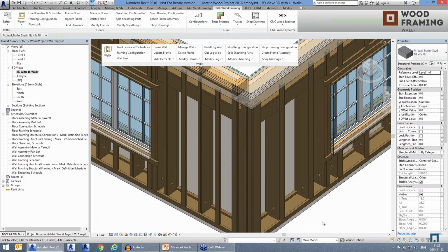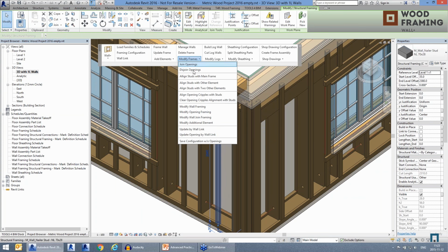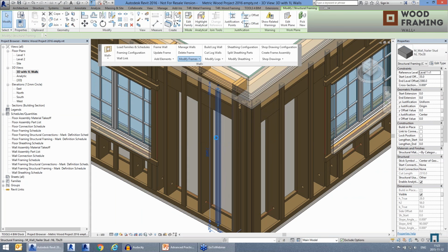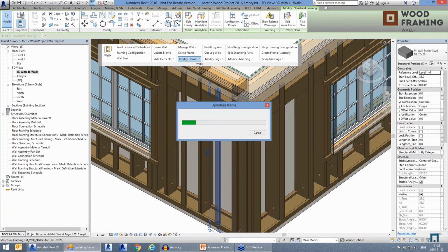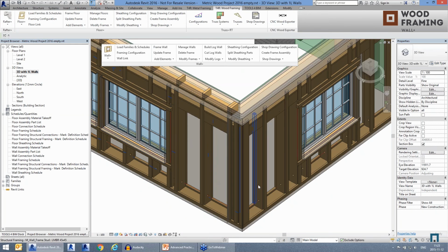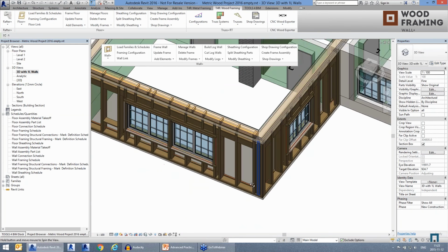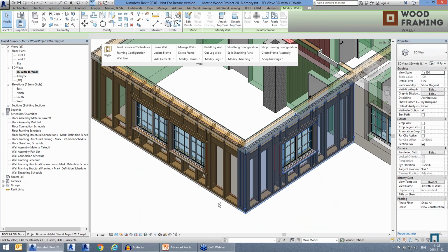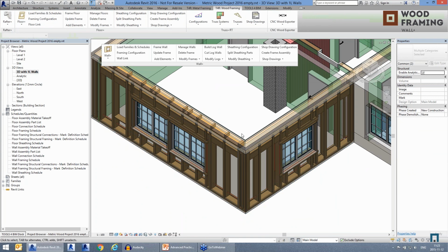So let's make alignment of that secondary layer. And as you can see, every frame is really structural framing, so all those frames will have analytical lines. I will show you later an analytical model, so later those frames could be used in calculation system. Okay, so we have everything now in this wall, and the last thing, we need to add sidings.